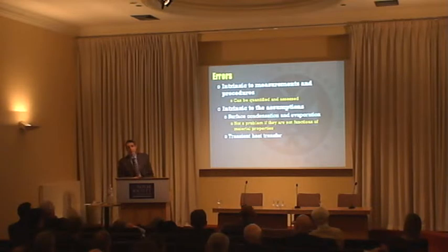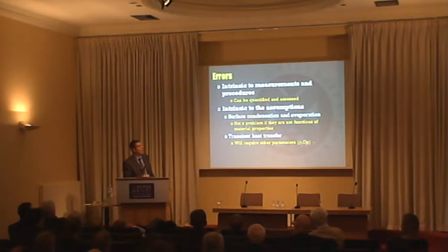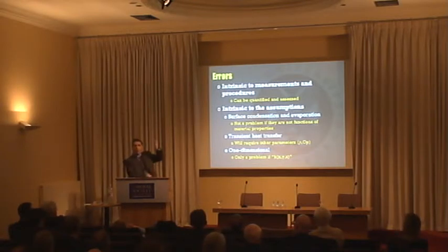So the question of heat transfer, that is a problem. Temperatures change during the day, so there might be a transient, and that transient might need a further analysis, and that further analysis is associated to other parameters that I have to evaluate in a different way. But in that case, I will have to create another test that enables me to get ρ and Cp, which are the other parameters that allow me to look into the transient part. Now, the one-dimensional assumption, well, I have to look into the corners, assess it, and all that stuff. But again, it's only a problem if the thermal conductivity is a function of the dimensions. So if the thermal conductivity is the same in all directions, then it doesn't affect my test.